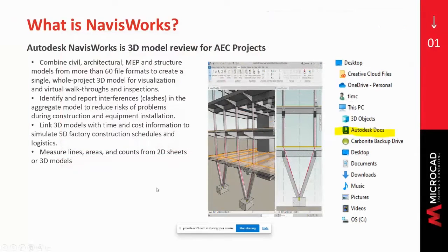All right, so let's talk a little bit more about what is NavisWorks. 3D model review for AEC projects. So it understands all the Autodesk AEC file formats. And you can see there that first bulleted item combines civil, architectural, MEP, and structural models to create a single whole project 3D model for visualization and virtual walkthroughs. Okay, but then significantly, we can then do clash detection. This is that second bulleted item.